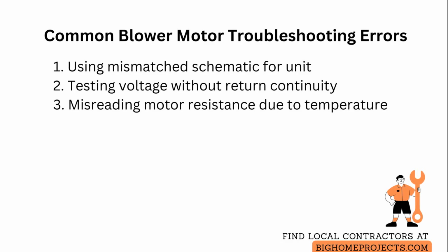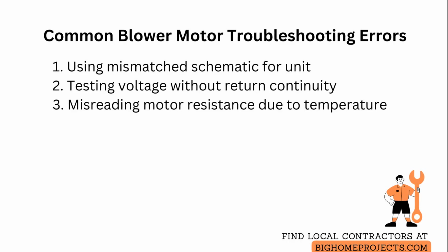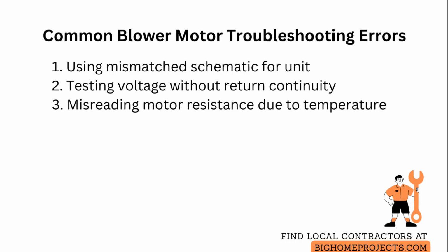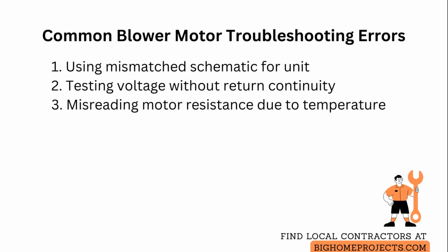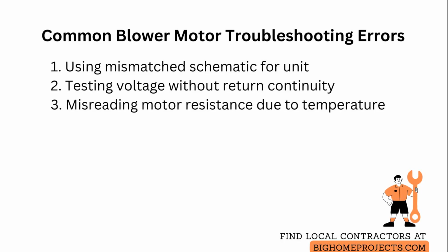Another frequent issue is performing voltage checks at the motor without confirming neutral or return continuity, which leads to misleading readings. Solution: reference the diagram to locate the true return path and measure between the correct terminals under operating conditions.